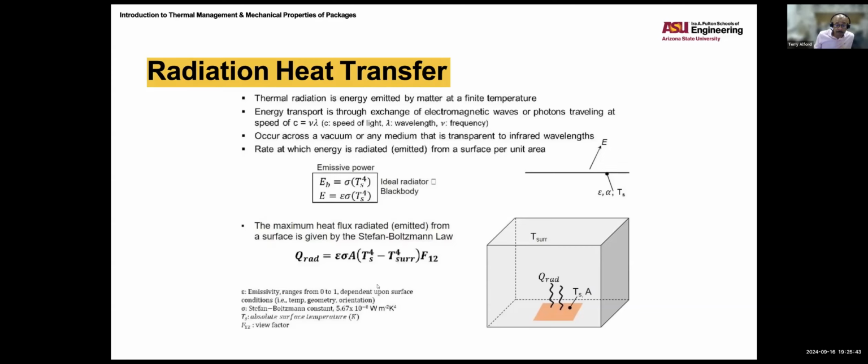Given the power, the power was 35 watts, so we multiply our resistance by 35 watts, and we end up with 92 degrees C. So the junction is at 92 degrees C, and we're able to remove that power to an ambient temperature of 30 degrees.